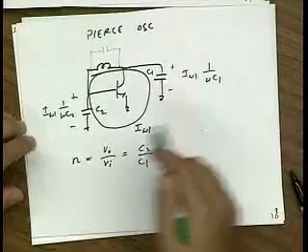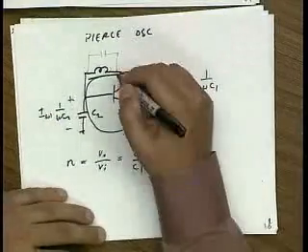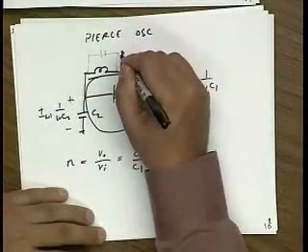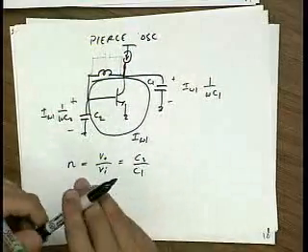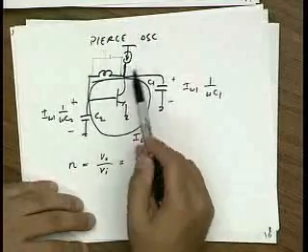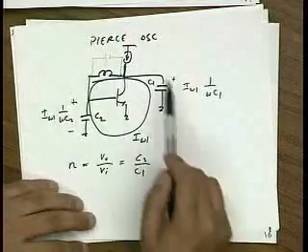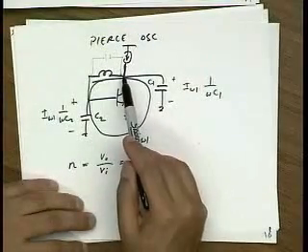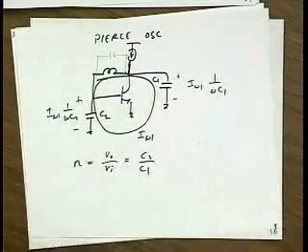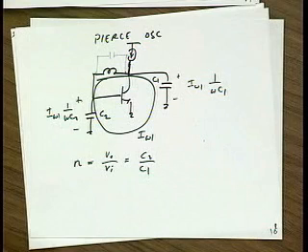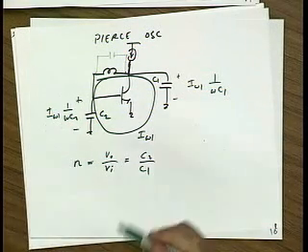So how do we bias this guy? We can just bias it by putting a current source right here. Or if you like, a big resistor to supply. Of course, the impedance of this has to be very large because I don't want to load this tank. Right? Any resistance at this node tends to load this tank. Okay? Question? The C1 and C2 has to be large enough to absorb the Miller cap across the base-emitter? Okay. Yeah, that's a good point.